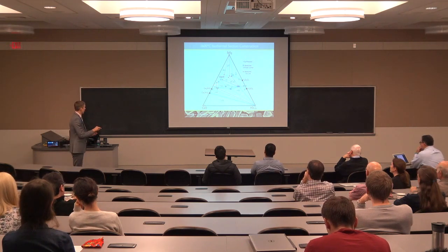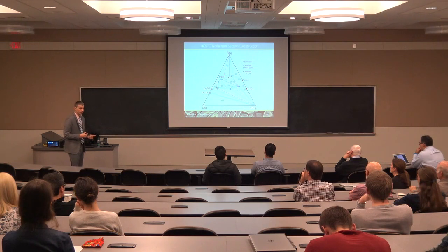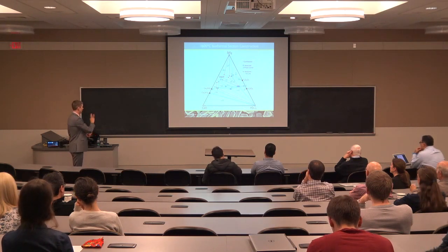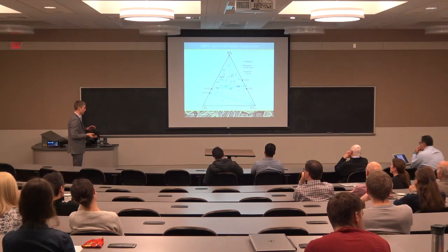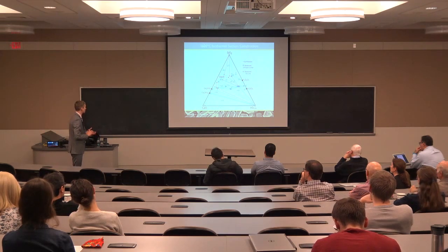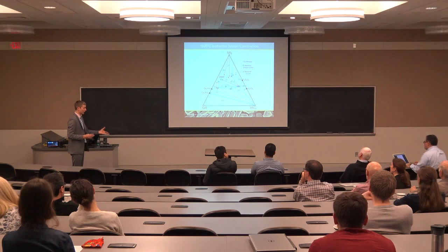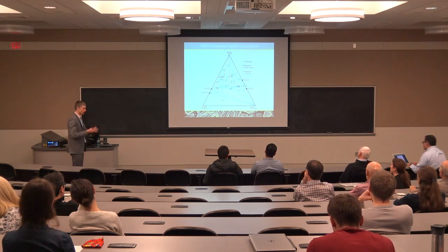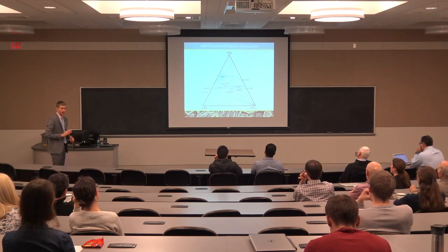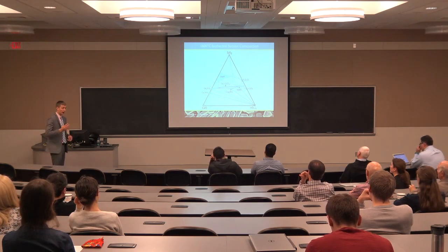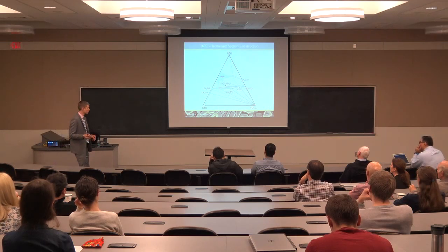And based on that, we now have some understanding of how readily yttrium substitutes into the liquid phase, and this information turns out to be really useful in fitting these Gibbs energy descriptions, in terms of what is the relative energetic effect of dissolving yttrium into the liquid as opposed to leaving it in a phase like apatite. And we can also use a ternary section like this to begin to understand the interaction, or better understand the interaction, between coatings and these calcium silicate-based liquids.